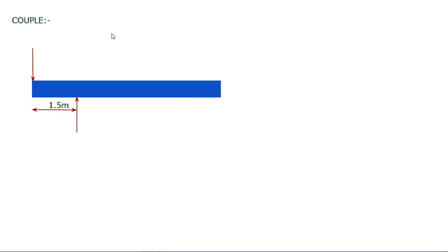Okay. Now the magnitude of force is given, that is 40 Newton, and this is the 40 Newton. So two forces having equal magnitude acting in opposite direction will form a couple. Okay. Now how is this couple formed here? What will be the direction of this couple? As it is acting anti-clockwise, you can see here, this is acting in anti-clockwise direction.